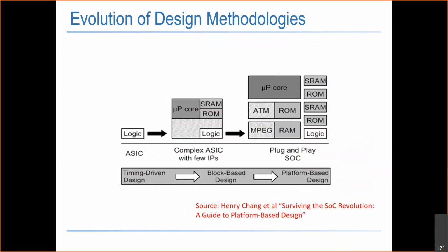Okay, so the design goes like this. You can do a complete ASIC from complete logic, okay? But this gives you a problem in modifying. So when you modify, you have to completely redesign it over again. Or you can have a very tightly integrated IP inside your ASIC. This makes it difficult for you to do plug and play. But a platform-based approach is that you can actually swap in and out these IPs with minimal, or you still have to do some integration, but it's not going to be as complex or as difficult as a tightly integrated ASIC, or even as a completely customized logic.